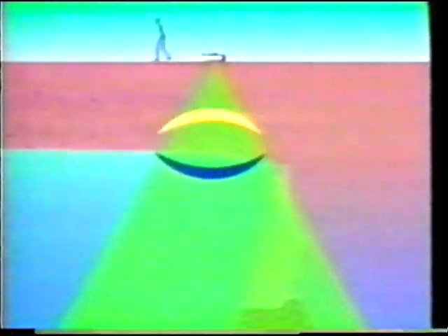For example, the ability to detect a water table is highly dependent upon the sharpness of the water boundary. A fine-grained sand layer could have steadily increasing water saturation with depth. In other words, no sharp water table boundary. This gradual change from dry to saturated sand is barely detectable. However, coarse-grained sands would have a sharp water table boundary, which would be easily detectable.